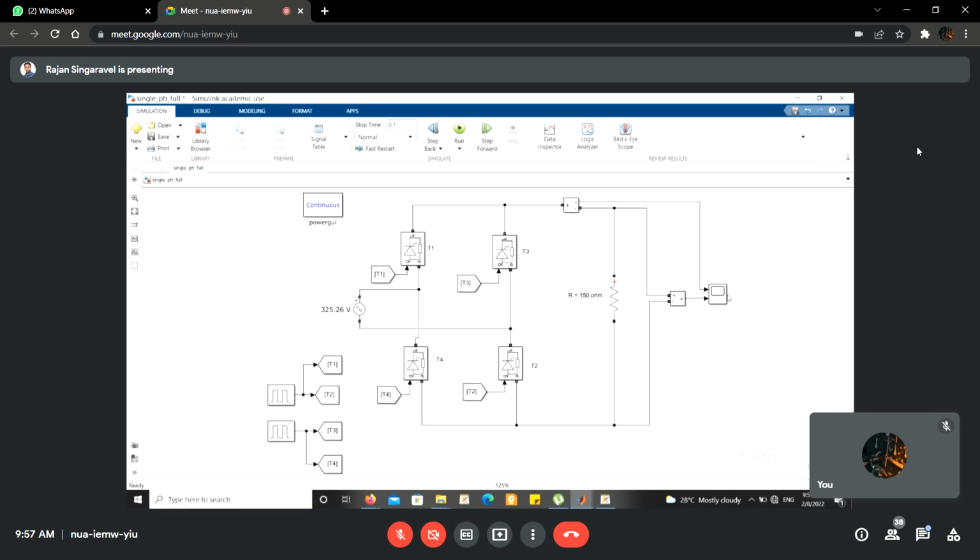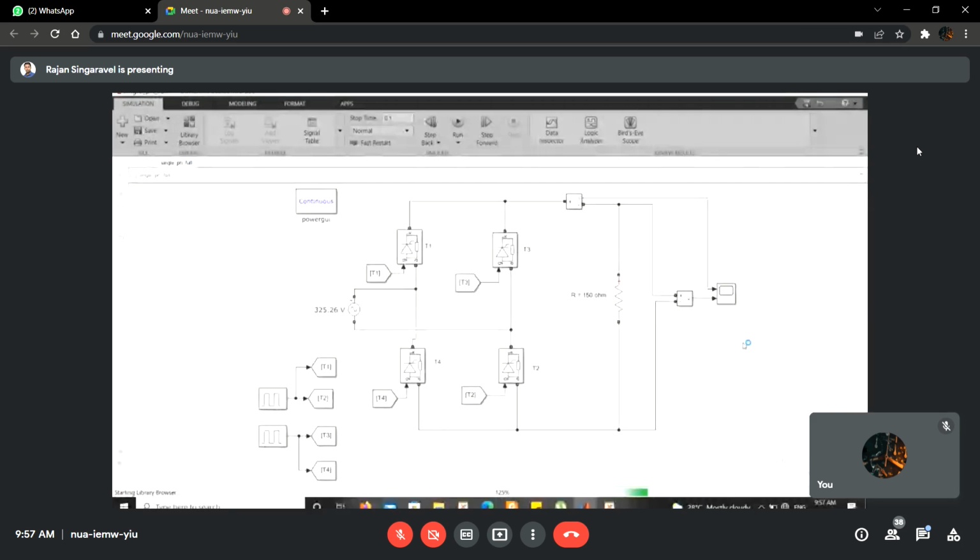Okay, that's all. This is a waveform, right? And when you increase alpha, you can see the waveform will change, and the average will be changing. So you can measure the average voltage. Let me measure and show you for two different values, to understand how the average voltage is changing.